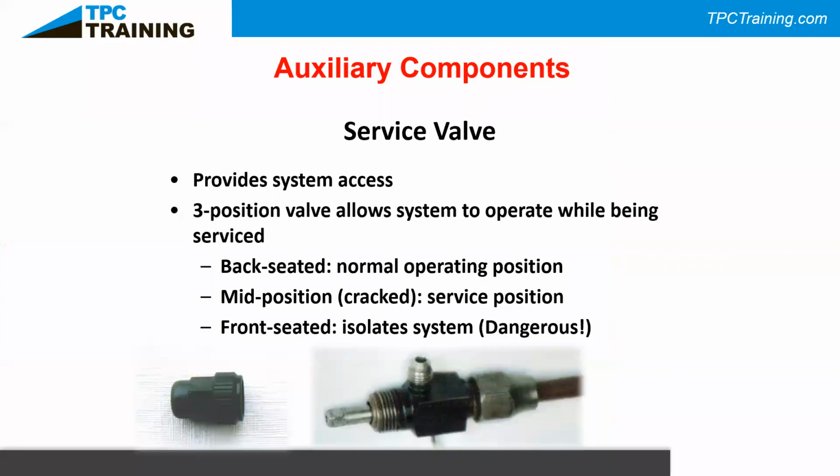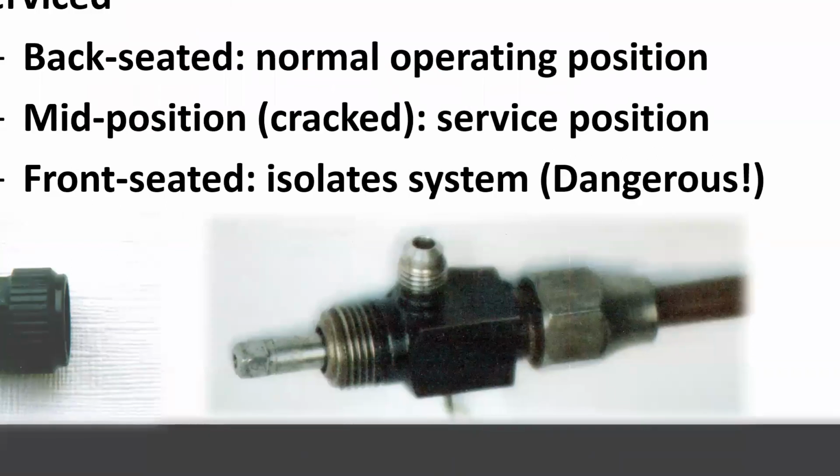One of the methods for connecting your manifold gauges is if we have what we call a semi-hermetic compressor. Semi-hermetic compressors are unique in that there's parts of the compressor that we can change. And this is what I like to call the manual access valve. So we're going to hook up our gauges to this center port right here that we have the cap off of. And we're going to have our gauge on here. And then by exercising this stem in and out, it's going to allow us access to that port to read the pressures on our gauges.